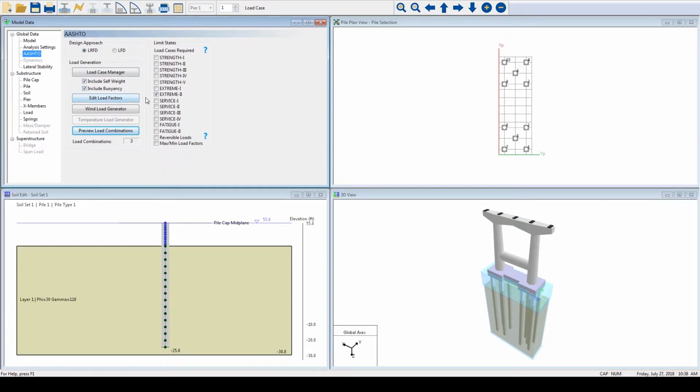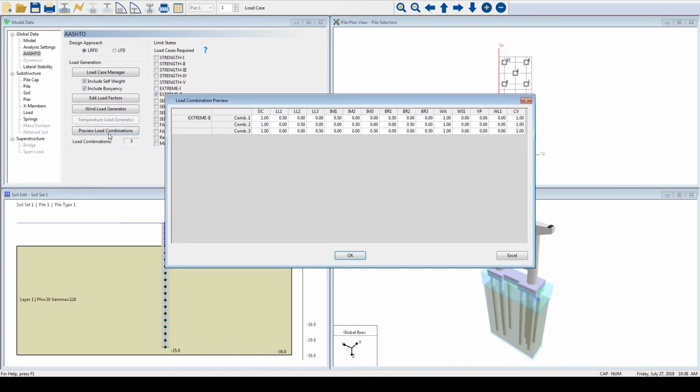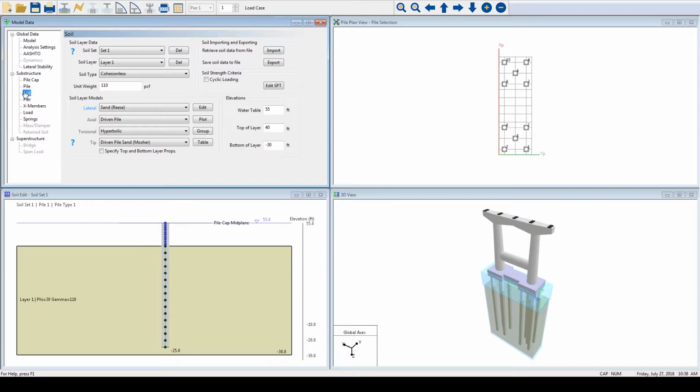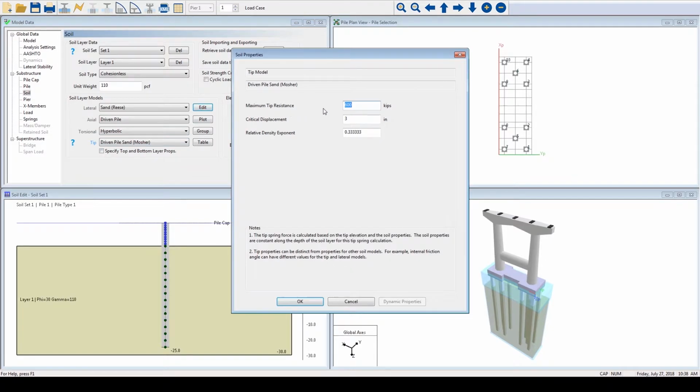For this model, we have AASHTO Extreme 2 CV selected. FB-MultiPier will conduct a minimum pile tip embedment analysis for each load combination while incrementing the pile length to iteratively reduced lengths. Typically, soil tip resistance is selected to prevent axial failure up to required ultimate capacity.